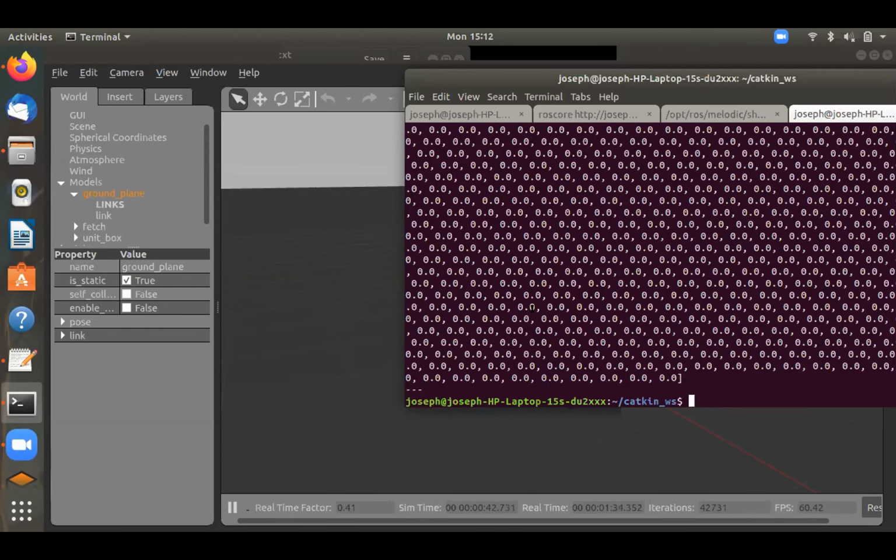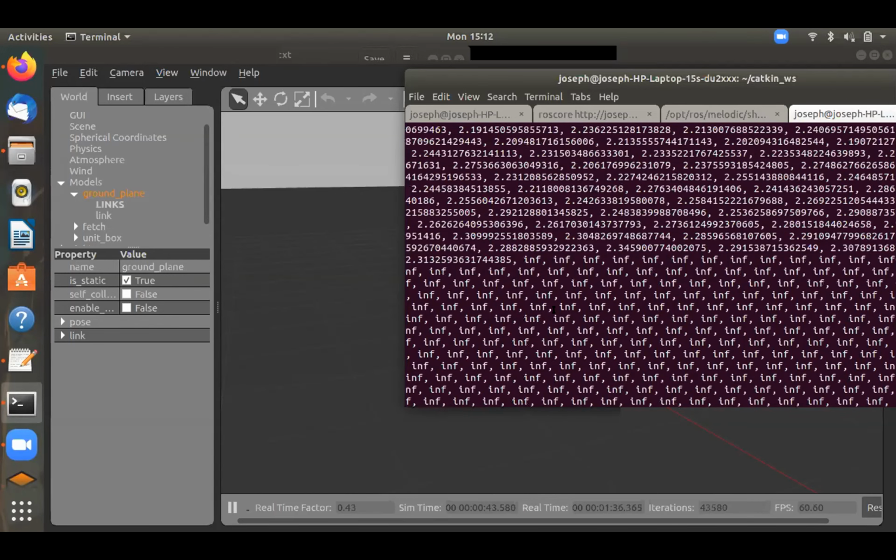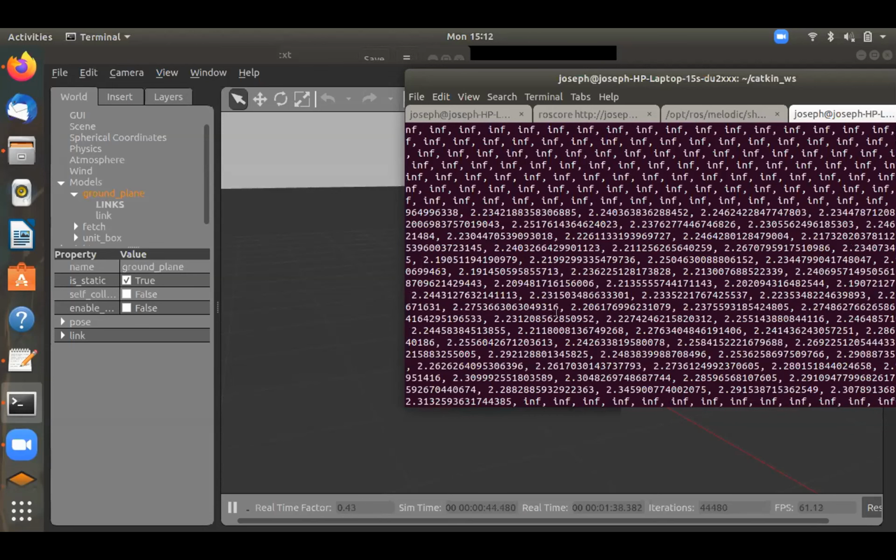Yeah, so you're getting the scan information. You don't need a separate package to read the scan information. All you have to do is subscribe to that topic, and then, just like I showed you today in MATLAB using the camera image, you can load that into MATLAB. Or if you want to code in C++ or Python, all you have to do is subscribe to that topic, right? The /base_scan topic, and then all this information in your laser scan will be available to you.